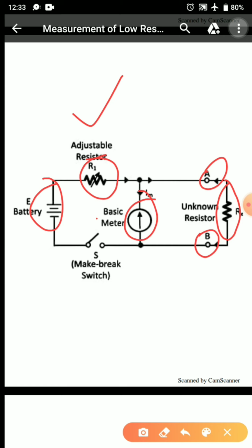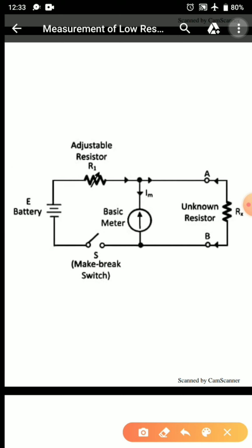Now it is necessary to have an on-off switch. Here an on-off switch is necessary because we have to disconnect the battery if it is not in use. What will happen otherwise? The battery will drain out. Why? Because if the switch is connected, it will make a complete path, and the current will keep on conducting and the battery will discharge. Therefore an on-off switch is necessary.